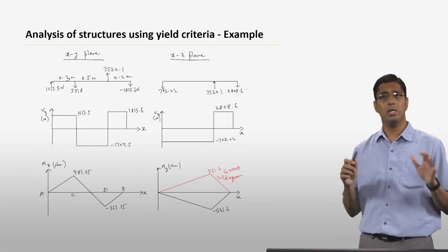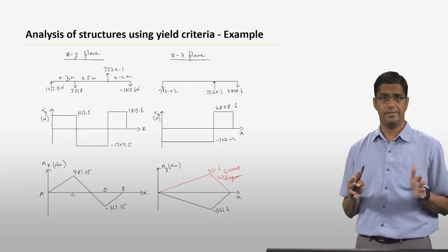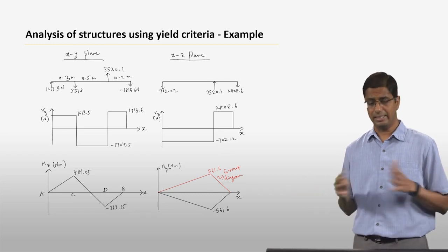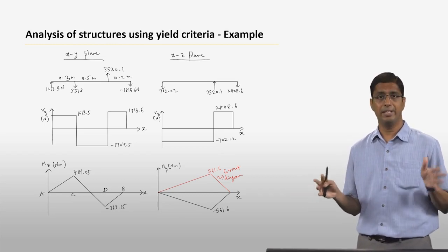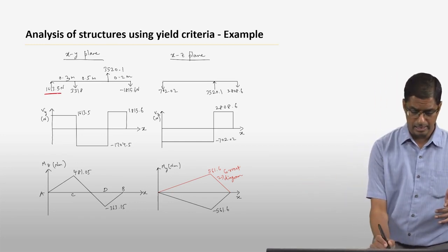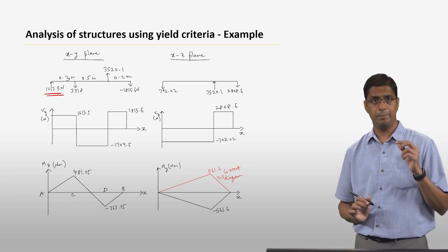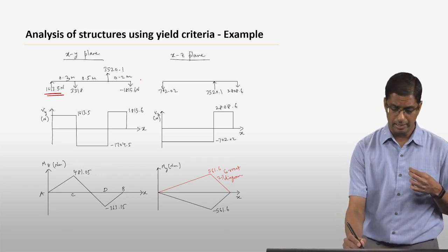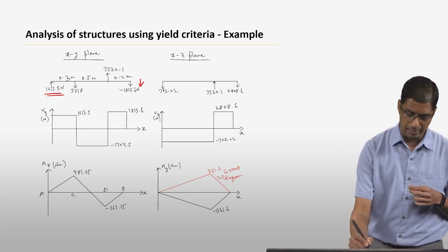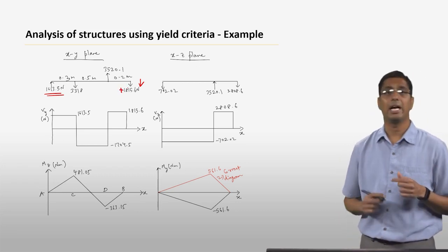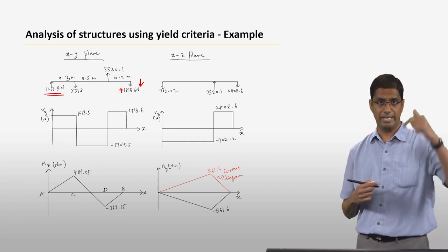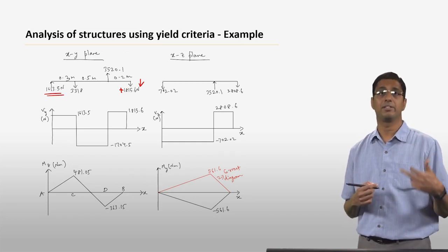Okay. Now, once we know all the reactions in the xy plane and the xz plane, essentially you can draw the free body diagram with the correct sense of the forces. So in this case, AY is acting up because AY was positive. On the other hand, BY is acting down. Okay, so I should probably have a positive sign here because I have already included the sense of the force in my free body diagram. The arrow is pointing down, so it essentially means that it's already negative.